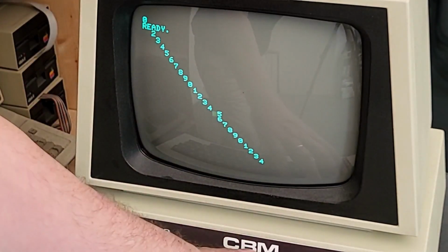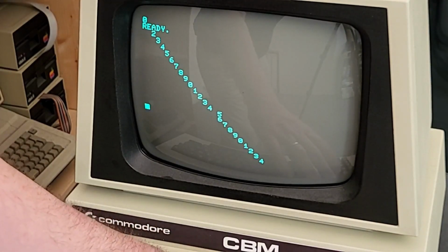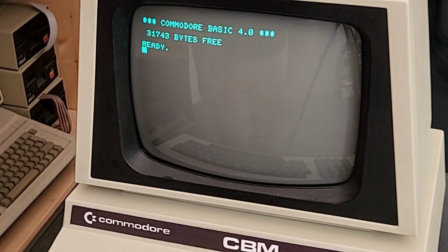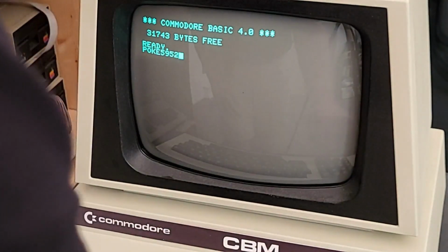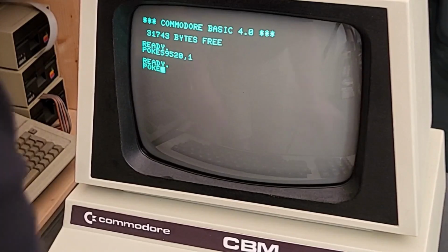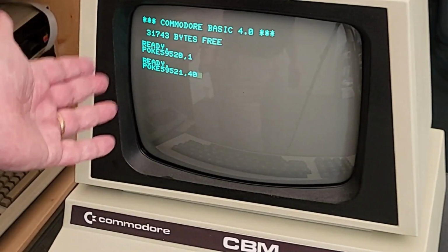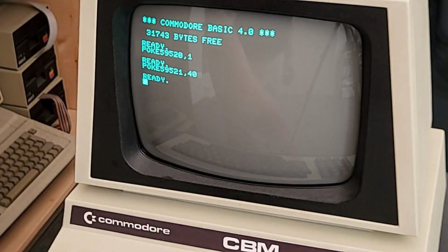You of course have to make sure that screen memory is adapted and filled with the right patterns and so on. But this is a way you can scroll parts of the actual screen. One other thing that is interesting here is if you look at register 1, which is the number of displayed characters per line. The usual value is 40, and this is even the value for the 80 column machine. I'll talk about that later, but you can increase that value as well.